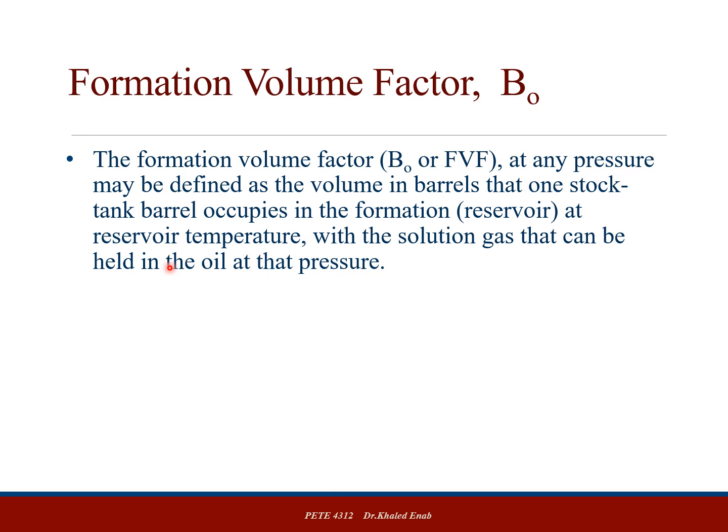Okay, so it may feel confusing, and if you still feel confused about it, let me know and we can elaborate on it more. But always keep in mind that the formation volume factor is always above 1. Not because the volume of the oil on the surface is smaller than the volume of the fluid in the reservoir.